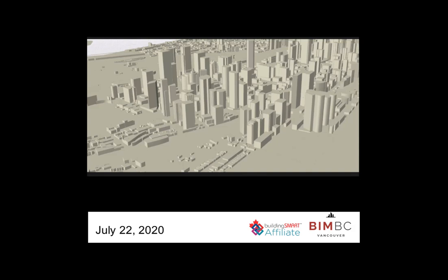And in this case, I said, okay, OpenStreetMap, fetch me all the building footprints which have height data and extrude them into a 3D form. And then this city model was converted into an IFC, because in an IFC file, you can actually store many, many buildings and many plots of sites.